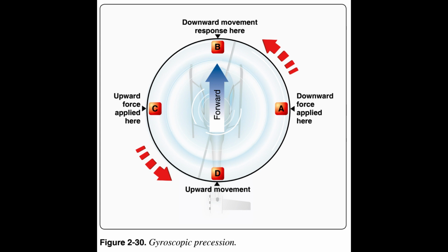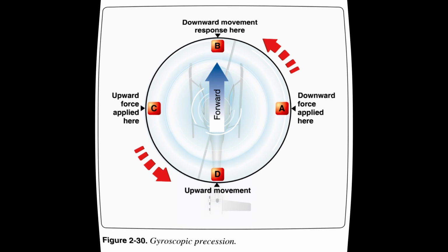Figure 2.30. Examine a two-bladed rotor disc to see how gyroscopic precession affects the movement of the tip path plane. Moving the cyclic pitch control increases the angle of incidence of one rotor blade with the result of a greater lifting force being applied at that point in the plane of rotation. This same control movement simultaneously decreases the angle of incidence of the other blade the same amount, thus decreasing the lifting force applied at that point in the plane of rotation.